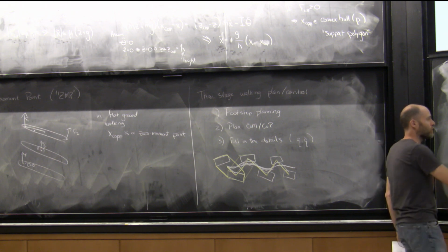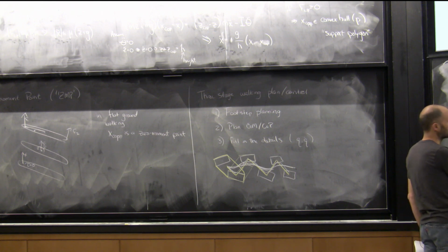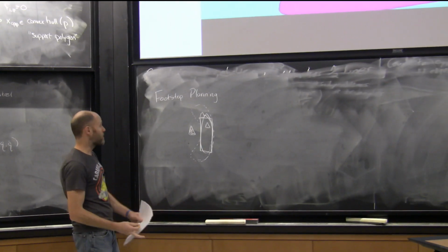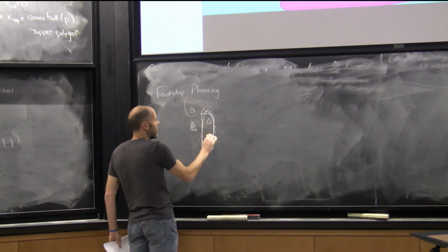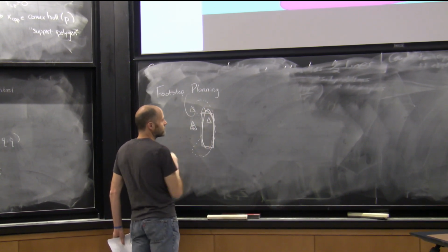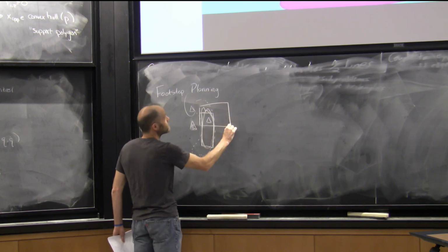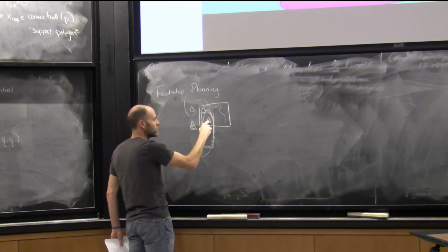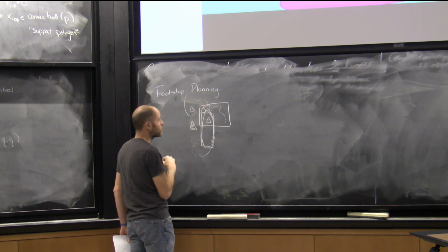All right, so we started off with a heuristic way to do the footstep planning. We made convex approximations of reachable sets, and then we started doing, for instance, nonlinear trajectory optimization to try to plan a set of footsteps. Given the reachable set of the robot, and some admissible regions where I can step coming from my perception system, I have to find an assignment of each of those footsteps that's inside these regions, in the order that goes through.